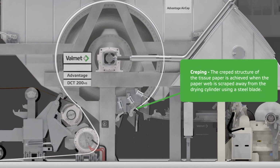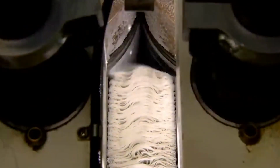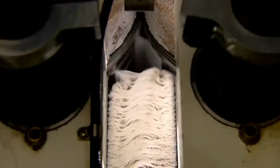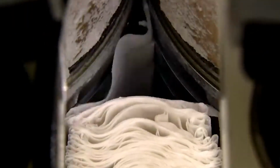Careful control of this stage is essential to avoid over-drying, which can make the tissue paper brittle, or under-drying, which can leave it too moist for packaging. Properly executed, the drying process ensures that the tissue paper meets the desired standards for softness, absorbency, and durability, making it ready for the subsequent steps of cutting, embossing, packaging, and distribution.